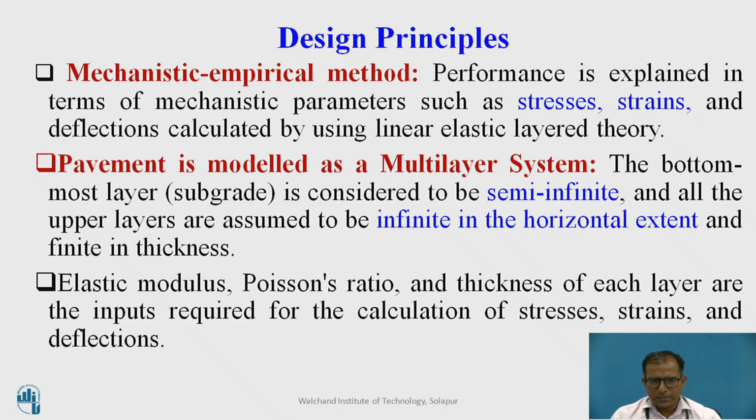Other parameters we should consider are the elastic modulus of all the layers, which we call the resilient modulus here, the Poisson's ratio of all the layers, and the thickness of each layer. We have to give these inputs to calculate the stresses, strains and also deflections.